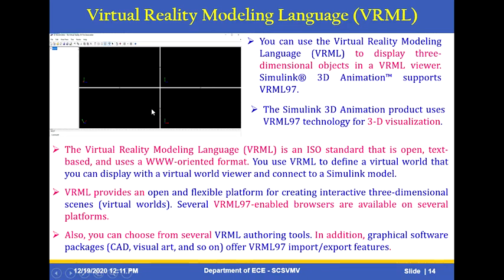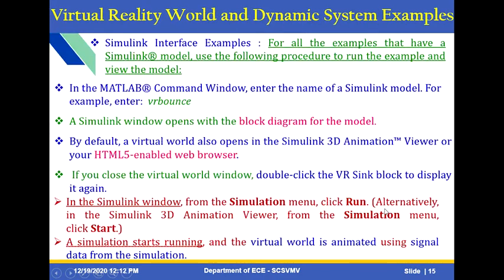You can use VRML to define a virtual world that you can display with a virtual world viewer and connect to a Simulink model. VRML provides a flexible platform for creating interactive 3-dimensional scenes, and we can choose from several VRML authoring tools. In addition, graphics packages, CAD software and visual art software also offer VRML 97 import and export features.